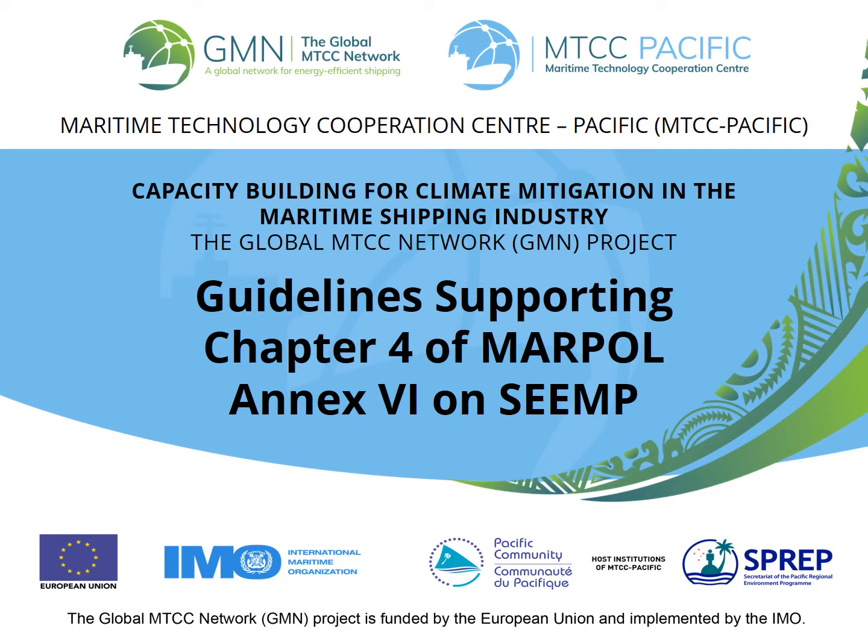The regulatory framework for shipping energy efficiency for new ships is to a large extent in place. For existing vessels, the SEEMP regulations can be implemented. SEEMP is only applicable to a specific ship and is used mainly on board ships, and its contents are primarily implementation orientated, which means that the strength of an SEEMP should be on how to implement the energy efficient measures at the ship level, together with a good definition of what has to be done and ship staff's roles and responsibilities.